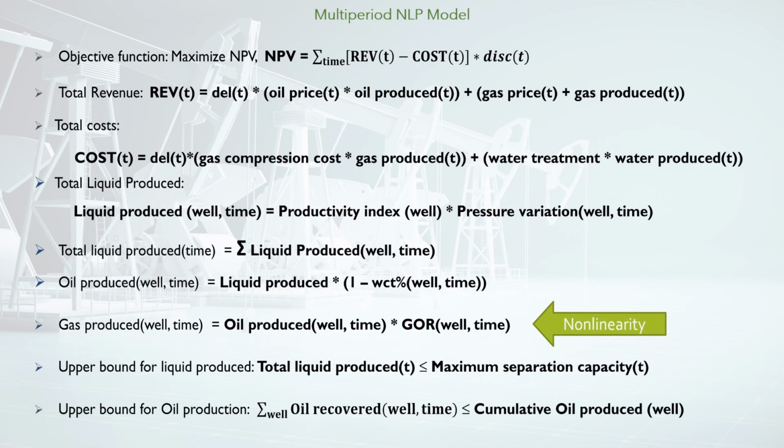The image presents the conceptual formulation of the model. The components of the objective function are: oil sales income, total liquid production cost, total water injection cost, and drilling cost. These economic values are summed over all the periods of the planning horizon, discounting them based on the beta discount factor. The model is a mixed-integer nonlinear programming problem, MINLP. The main constraints are: discretized reservoir correlations, nonlinear pressure drop correlations, well placement equations, and component flow rate bounds.